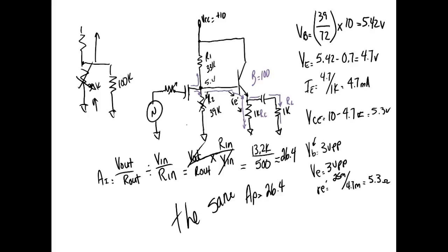So voltage collector to emitter, we should expect it to do what? Is it going to go up or go down? Huh? Saturated transistor. What voltage do we use to determine if a transistor is saturated? Voltage collector to emitter. If it's less than a volt, we consider it to be what? Saturated, right? If it's equal to VCC, it is cut off. If it's in between that, we consider it to be in the active region. We ought to put a scope on this and let y'all see this. Man, it's going to be really saturated.